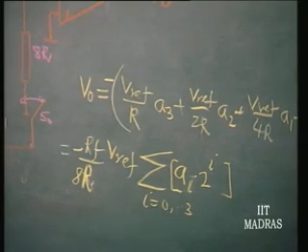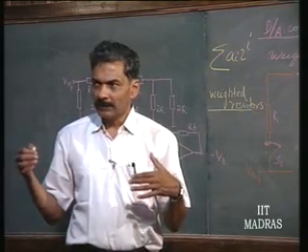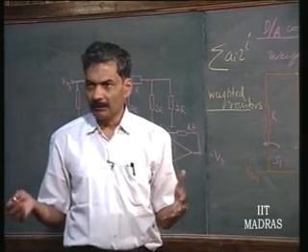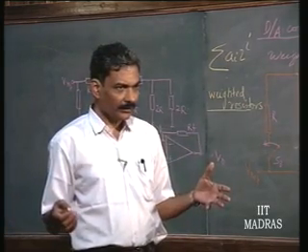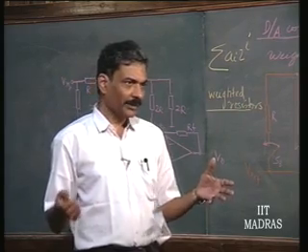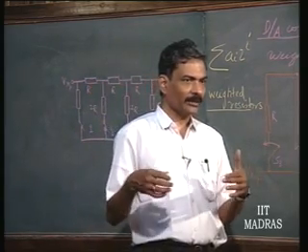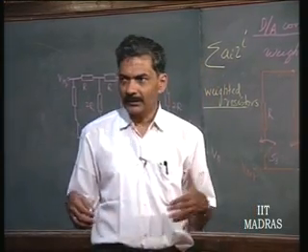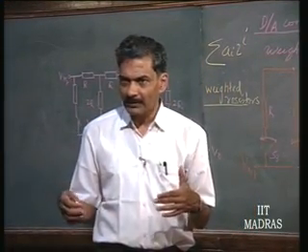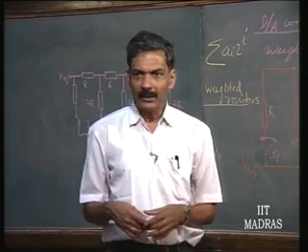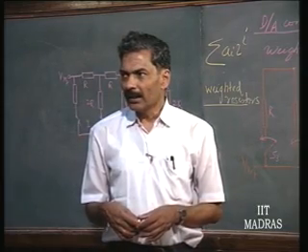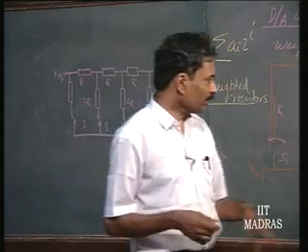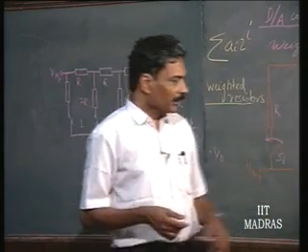If you want very precise D to A converters, you have to go in for thin film or thick film components as resistors, because we have seen that resistors in monolithic form have very poor tolerance. Ratio tolerance, even though better than absolute value tolerance, is hardly acceptable, something like 1 to 3%, which is not acceptable for precision converters.